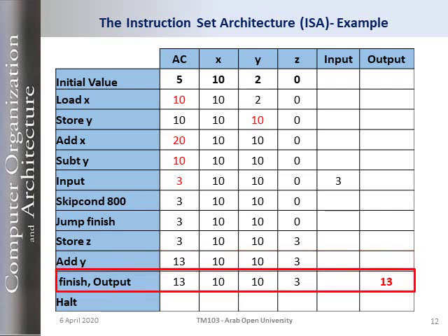And now the next instruction is Output. We will ignore this. This is just a naming. It's just like a variable or a name or a tag. We can call it a tag. We'll talk about this in more detail later. So Output means whatever is in the accumulator we'll put it on the display. So 13 will be outputted here. And then Halt means that this is the end of the program.